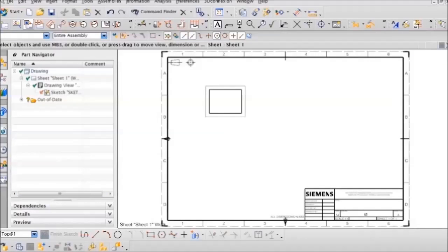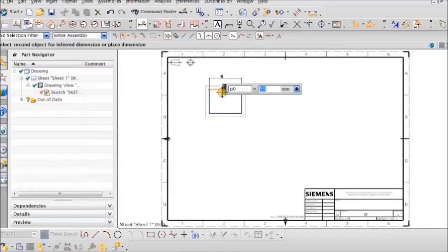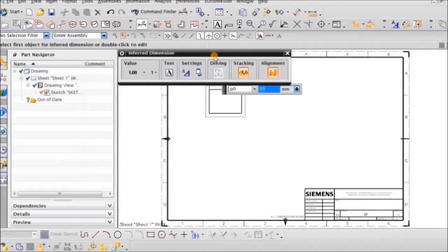Tip number 4. It will show you how to define the sketch view which is updatable and would follow the parametric model. Over here you can see that I have a sketch view, and to make the sketch updatable I would add a dimension to the sketch, and here you have to make sure that it is a driving dimension.